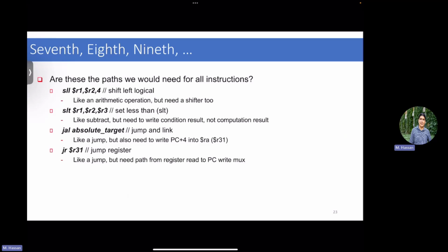From what we discussed so far of our types, the register file simply has a write enable here, right? Because in case of a store, I simply have to disable the write enable. I'm not writing to the register file. In case of all the other types we had so far, even in case of a branch, you have to disable the write enable, because in branch instructions you don't write to the register file. But in case of an add I and load, you are writing to the register file. So this write enable will only be enabled for instructions that write to the register file, right? That's the first thing. Then we have this mux here that simply determines our register file destination, from where it should come in the field of the opcode.